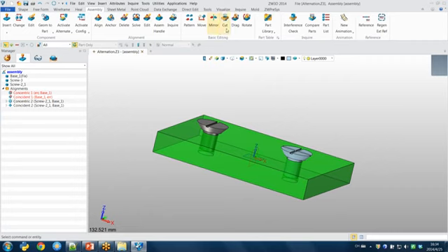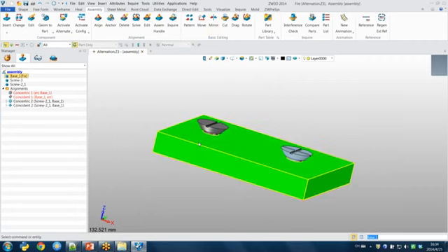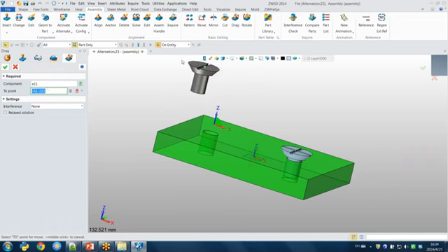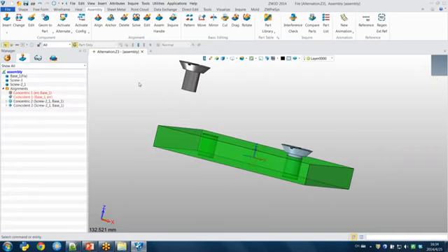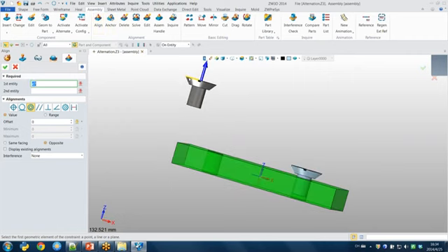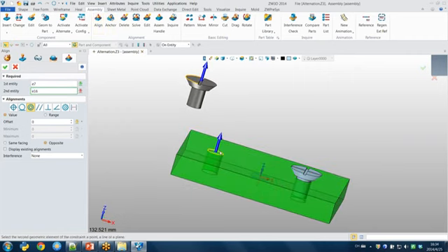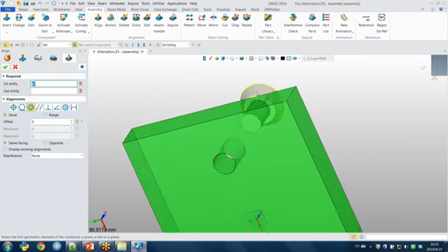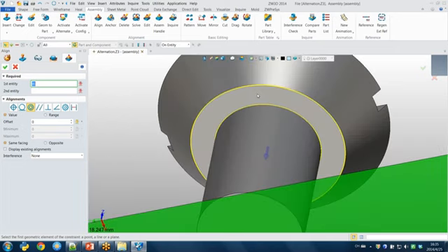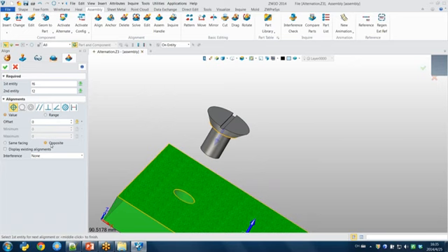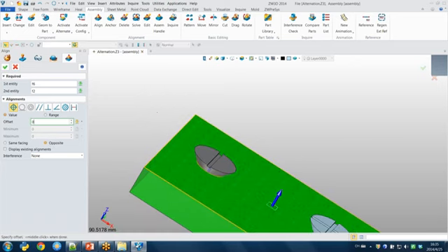But screw 3 doesn't have a connection with the base. You can test it: drag it, move it. So I also need to make the alignment. Choose the edge, same face, alignment, face offset, give an offset.